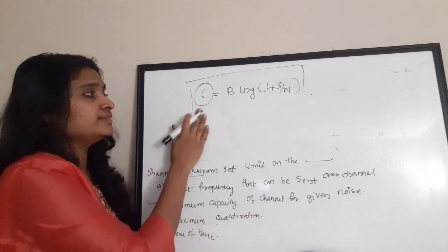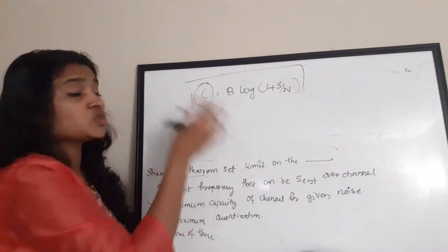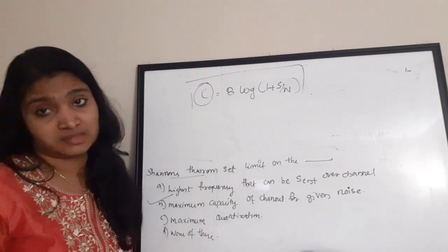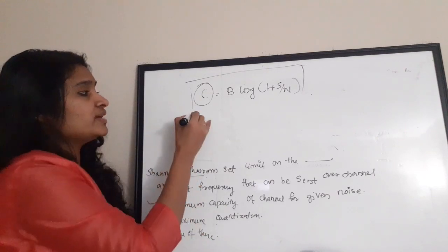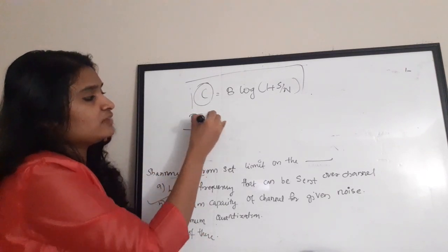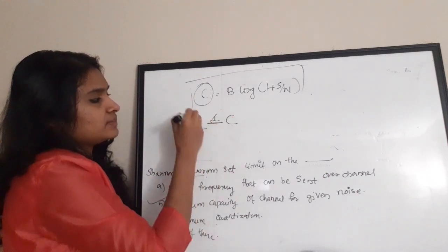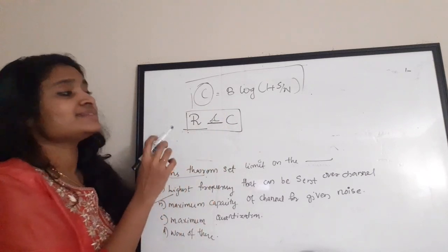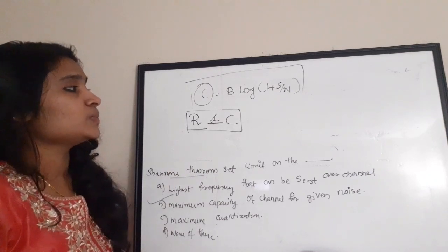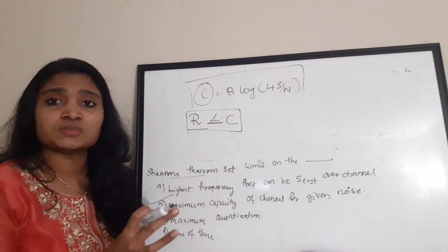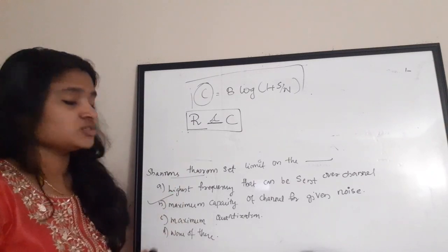So this Shannon-Hartley theorem is saying that C is the maximum capacity possible for a communication channel without errors. That is, within the given error limit, this much of communication is possible. So when selecting a data rate R, we have to select R such that R should be less than or equal to C. Always this rule has to be followed for the data rate R. Maximum capacity possible is C, so the data rate should be less than the capacity. Correct answer here is option B.